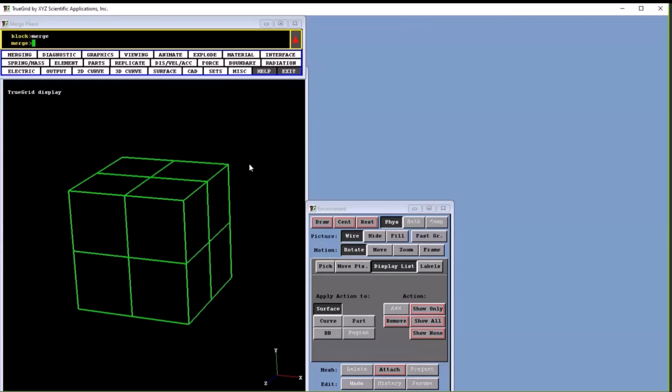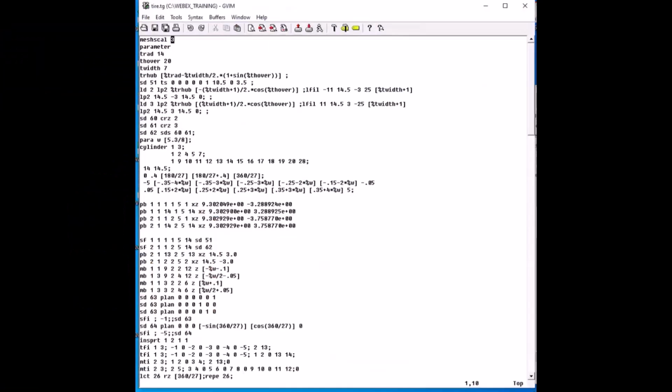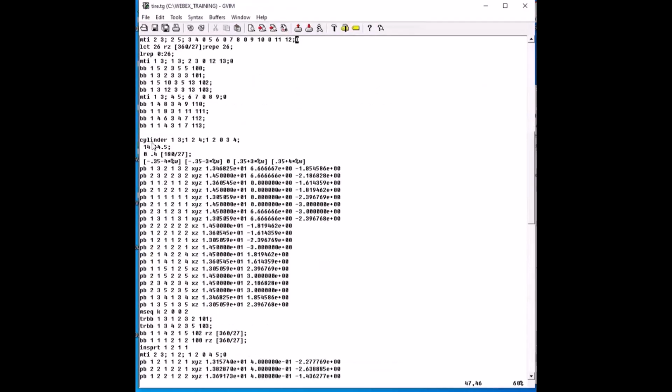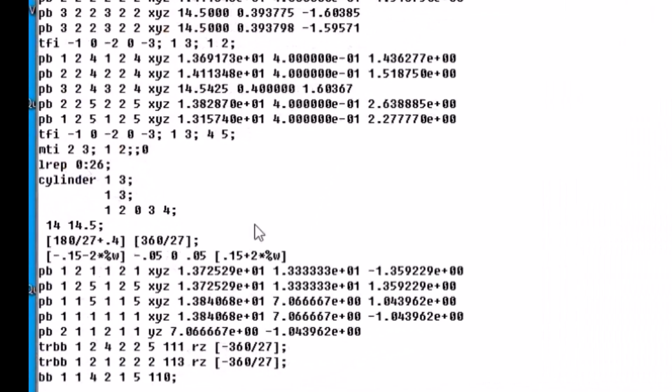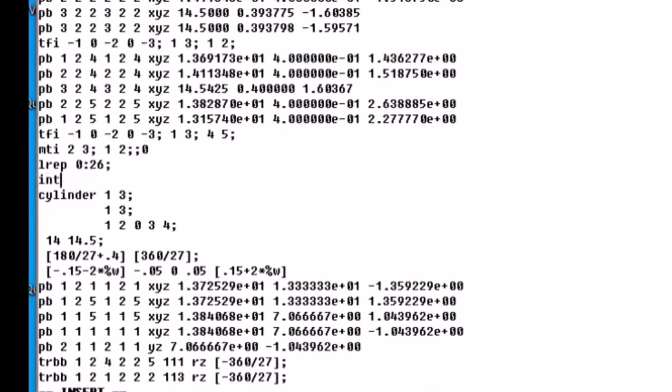And what you do is you put the word interrupt into the command file. I'm going to show you how I do that. We're going to use our tire problem to show you an example of how the interrupts work in the TG files. Now here we've got one part. Here's a second part. Now suppose that I wanted to make a change to this second part. I'll go to the end of that part, and I'm going to insert the command interrupt.